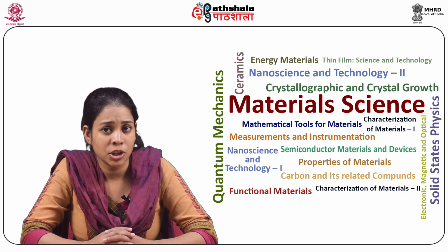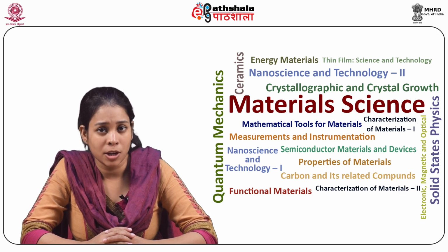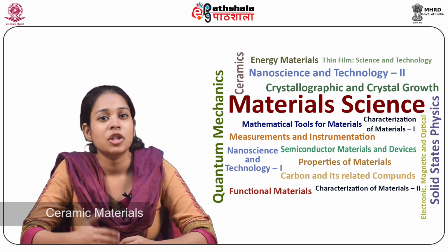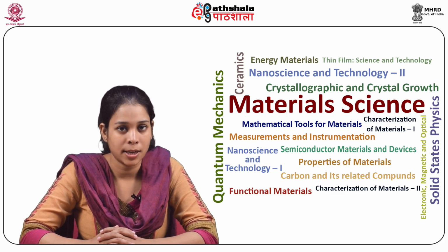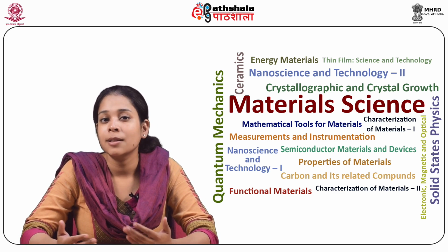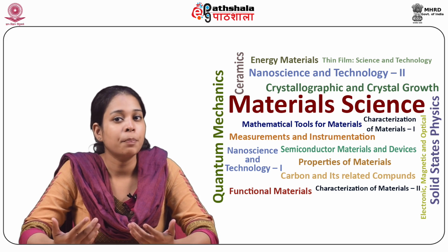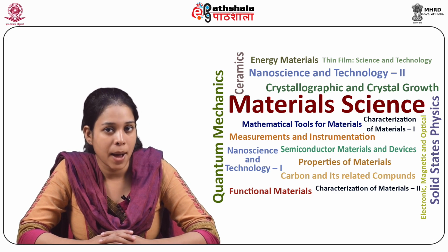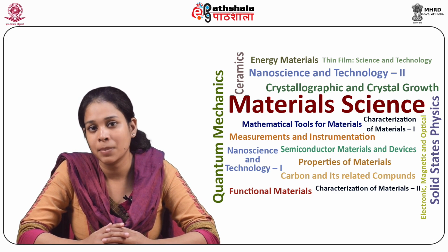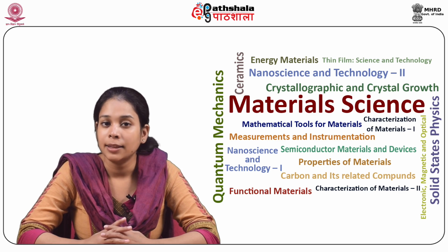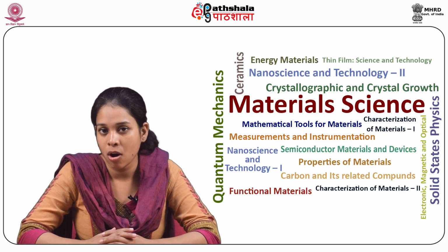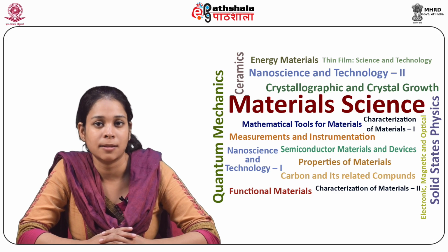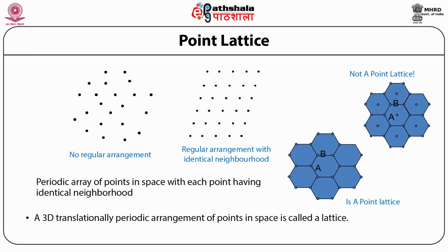Together, this information will form the basis of structure in ceramic material, which are typically bonded with the mixed ionic bonding and covalent bonding. Subsequently, we would discuss the structure of ceramic materials with purely covalent bonding, followed by a rather detailed description of ceramic materials with ionic bonding. And these are essentially based on packing of ions, closed packed forms where cations fill the interstices. So before moving further, we will first discuss basic crystallography.